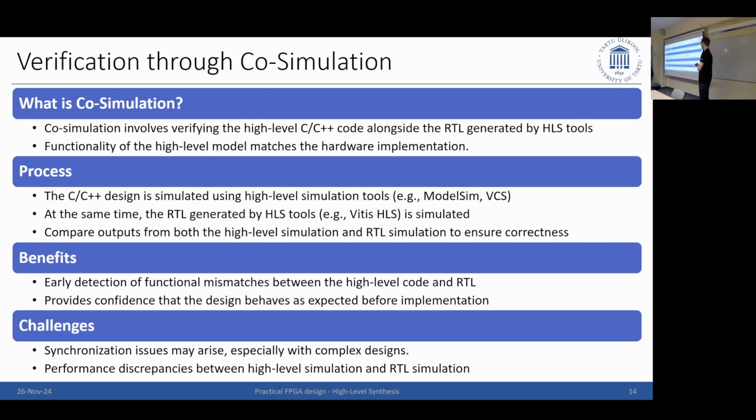So we use ModelSim or whatever for the co-simulation. And at the same time, the RTL generated by the HLS tools is also simulated in ModelSim or Vivado, for example, or whatever tools they use in the background, right? It doesn't have to open Vivado, you can just use a sub tool. And what is the nice thing about this? It will automatically compare my results and tell me good or bad, which might not be all I need, so I might still have to dive into it, right? But at least I know that my result is the same.